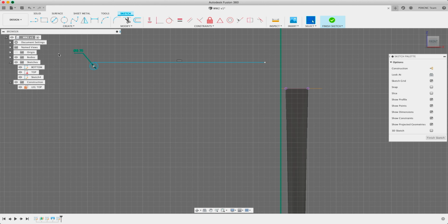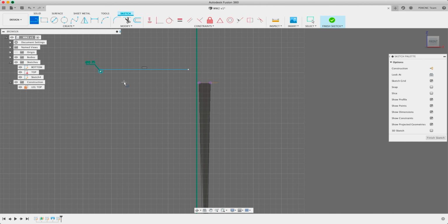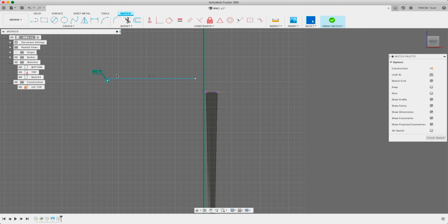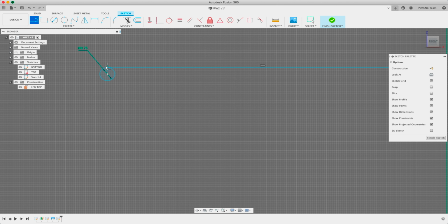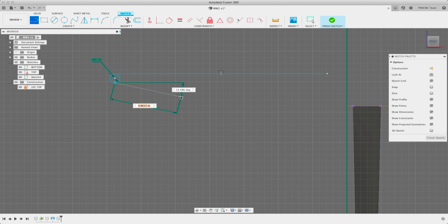We're going to type L for line again. If you're not catching what I'm doing here, I'm drawing the profile of my table. So you can think of it as a section, but we'll use it to go all the way around the table with our sweep command. So let's click another line here. Click, there's going to show a tangent at the bottom here. Click there, or wherever you'd like it to be. I think that's a nice angle.